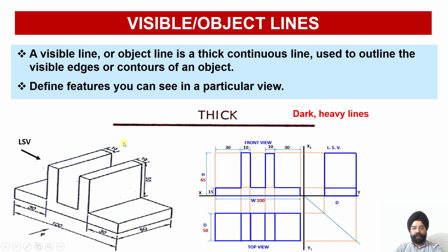If we look at this object from the top, obviously this surface will be available, then the second surface will be visible, then the third surface, this will be the fourth surface, and this will be the fifth surface that will be visible. You can see surface 1 corresponding to this. We have one rectangle corresponding to this, again drawn dark. Then there is a second surface corresponding to this web. This is the first web. This is the crest portion over here, so this is the crest portion rectangle. This one is the second web. We have drawn the second web again dark, and this rectangle is the bottom surface over here. So this is again a rectangle.